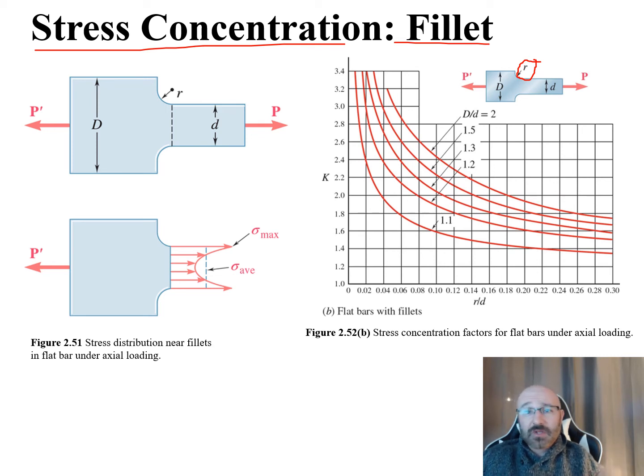This is a really great resource to reference back to as you're getting into some of your ME124 labs, or if you're doing any material testing where you're doing some tensile tests and you use some dog bone specimens, that radius quickly becomes important. And we didn't really discuss that too much before when we talked about tension testing. We're really talking about that cross-sectional area, based on this D value right here.